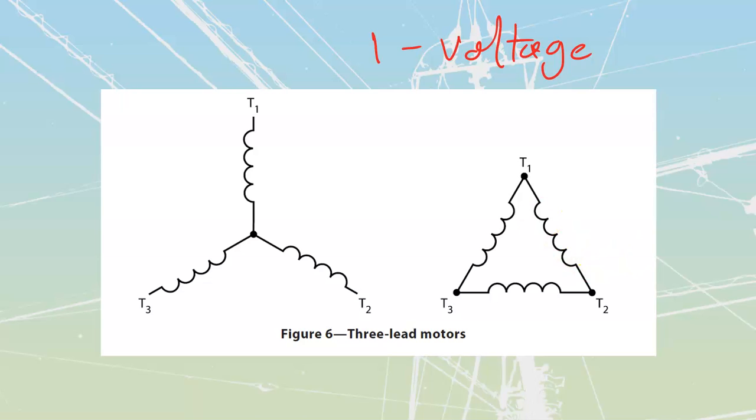This would be a load at that point. If I were to lose one of these here, then I'm going to have 2 of these that are still connected at full line-to-line values of voltage, which would mean that a delta type of motor will be able to run single phase. Okay, when it loses a winding, it's going to be able to run in single phase, and we're going to see that thing just kind of grinding through. It's going to be pretty hot, etc., because these two are going to be trying to carry all the work.